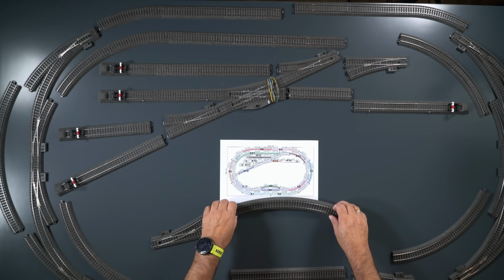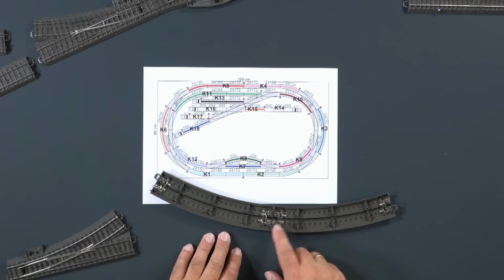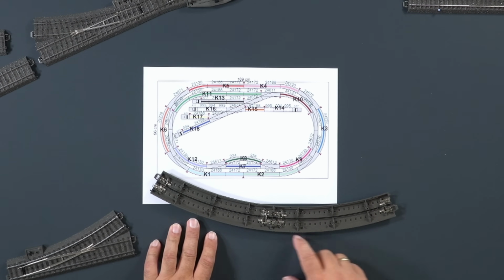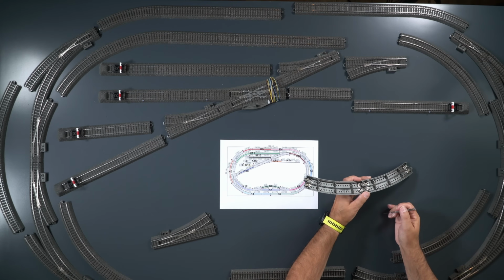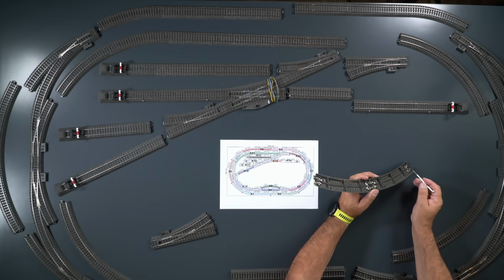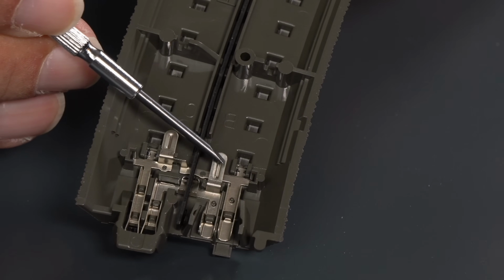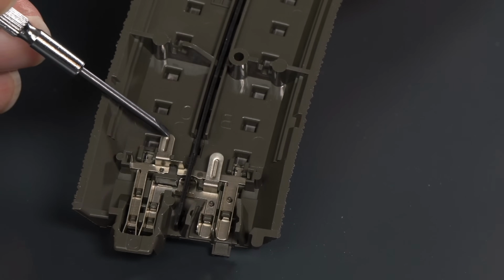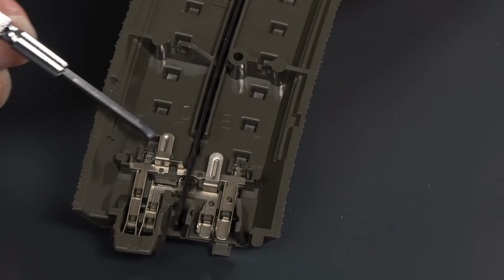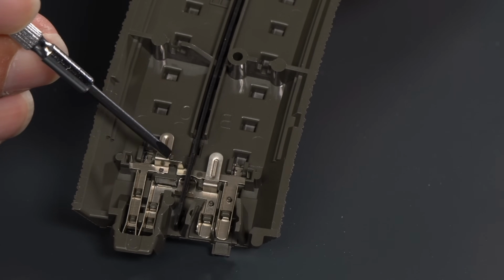But in addition to that, our turnouts are also interconnected, which essentially means that these connections I have here now also need to be separated. Now, this is our track, and of course we have the spot where the traction current is introduced into the track for the center rail, and on this side, this is the neutral conductor, which runs from here across this bridge to the other side.